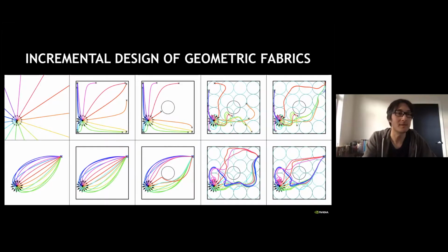So we start with this Euclidean behavior, which is just a straight line. If we choose a target and try to optimize over the top of it, it ends up bending that behavior to hit that target. We can then add joint limit avoidance, basically a boundary here, and layer it on top of the previous one, do the same thing, and we get behavior that, it's a little subtle here, but it's bending a little bit more to get there.